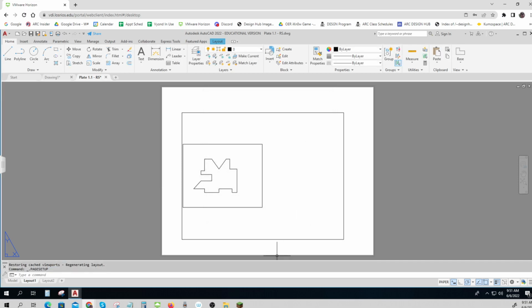So that's activity 1.1. Then in activity 1.2, this is called a viewport. It's already on there, and if I click on it and right click on it or hover, it says it's a viewport. And that's just a window on my piece of paper that shows my model. And we'll get into this a lot more later on.